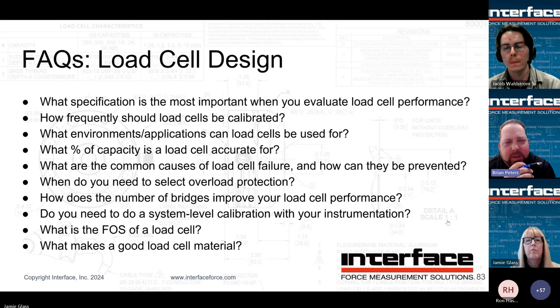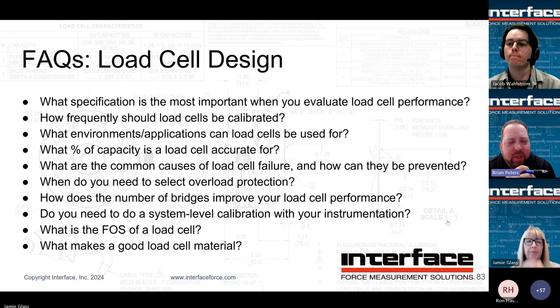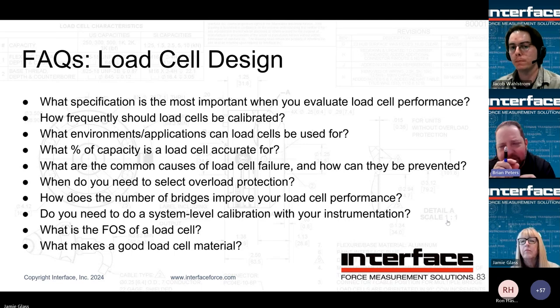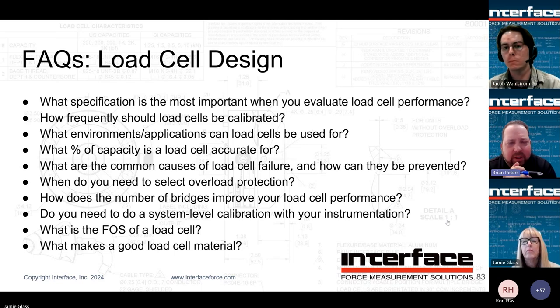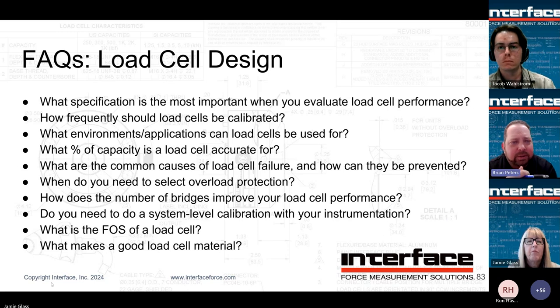Yeah, we typically recommend tighter intervals as the load cells are newer. They get better with age and more stable with age. I'm talking very, very small amounts. So typically customers would recal at least on an annual basis until they have good confidence in repeated cals to say that they can be extended. We've done that. Some of our standards, for example, we're able to extend them out a couple of years. So.